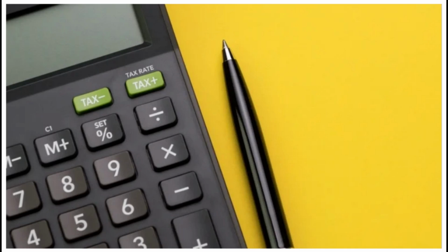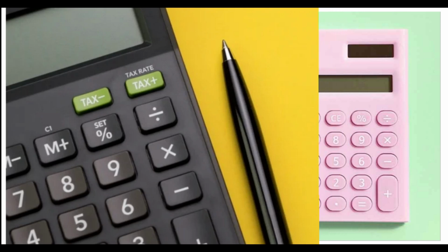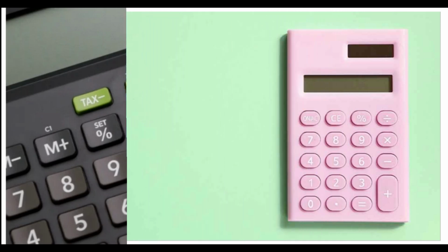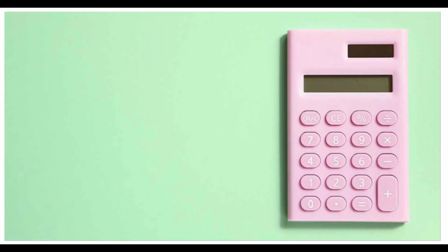The numbers in the X and Y registers are then loaded into the ALU and the calculation is carried out following instructions from the permanent or non-volatile memory. The answer, 34, is shifted back to the X register. From there, it is converted by the binary decoder unit into a decimal number, usually binary coded decimal, and then shown on the display panel. Other functions are usually performed using repeated additions or subtractions.